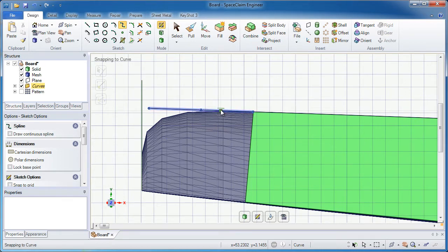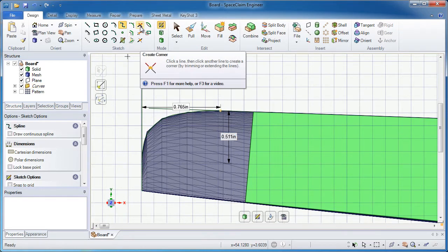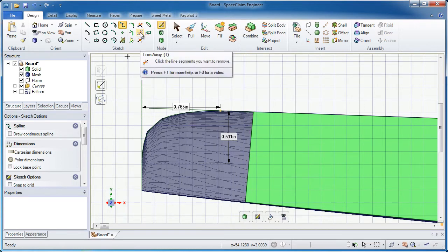If I hold down the Alt key, then I'm ensured the spline that I'm starting is collinear to that first line. So we'll start clicking on some points. You really can't put too many in here, but don't go crazy with too many. So when I'm done, I hold down the Alt key to solidify the last point and put that on that vertical line.